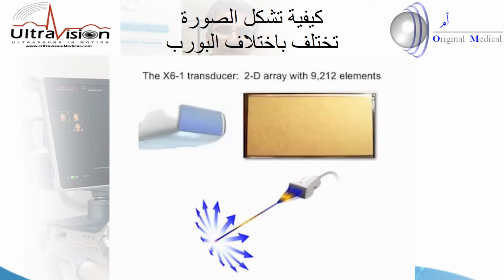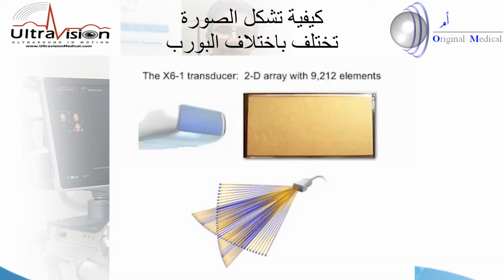One of them is in a conventional beam mode, but also, because you can steer the beam in the elevation direction, that beam mode can be translated without moving the transducer, and indeed you can make two or many more simultaneous real-time beam mode images of adjacent slices. The transducer can also image in the orthogonal direction, simultaneously with imaging in the long axis direction.